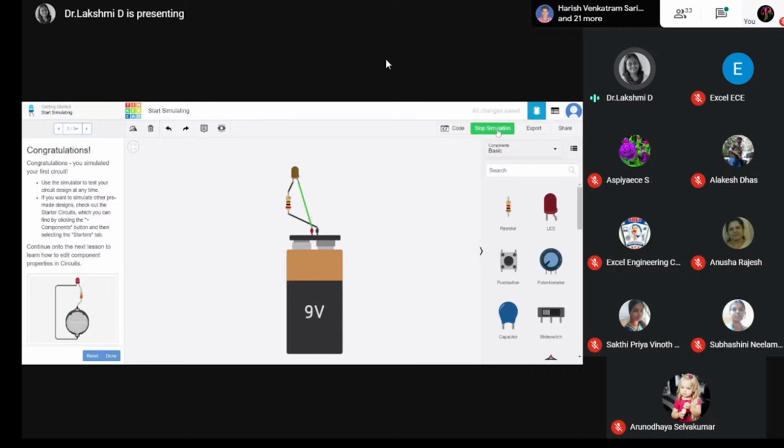Now let us look into the first code. You need to set pinMode. The 13th pin I am using is an output pin. We need to write the code. pinMode, this is the syntax. pinMode, 13th pin, I want to use as an output pin, semicolon. Only one pin I am using, as output. From here to here, the output is taken. Where will it go? It will go to the LED only. For the LED, we need not write anything. So now the pinMode setting is ready.